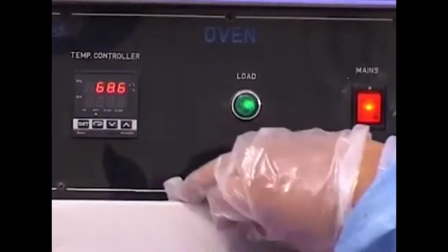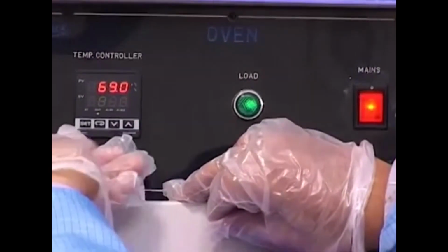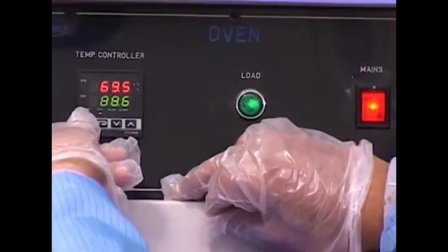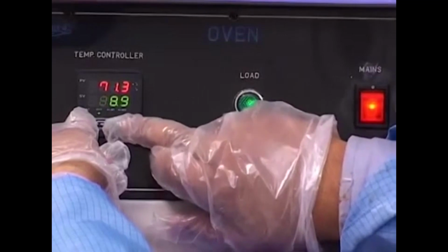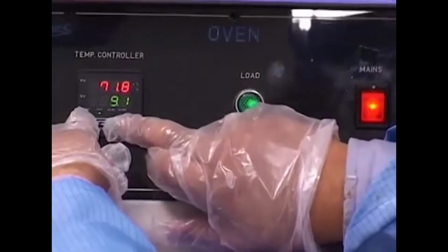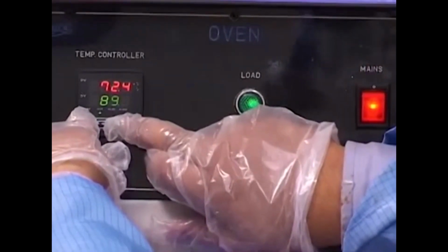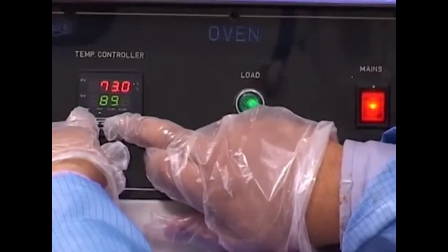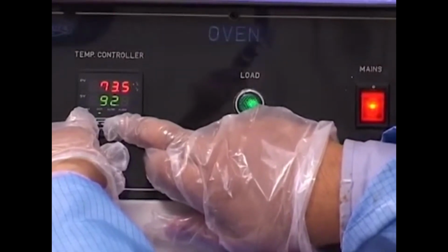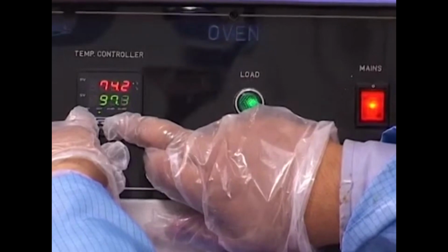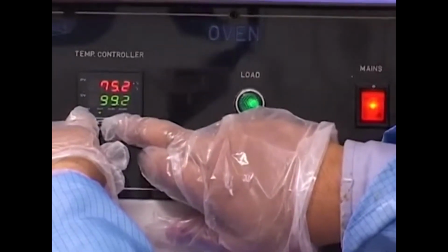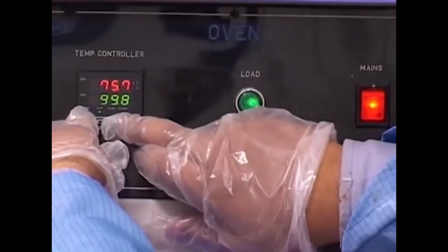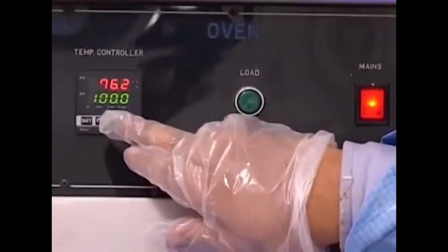In order to control this, you can see here there is a set option. So you press the set option and then take the up arrow or down arrow, and as you are seeing, the figure here, which is the SV or the set value, is varying: 89.3, 0.4, 0.5, 0.6, and so on and so forth. So we take this all the way to about 100 degrees, which is important for proper hydration of the wafer surface, and once you reach 100, you leave the set key, and this is now set at